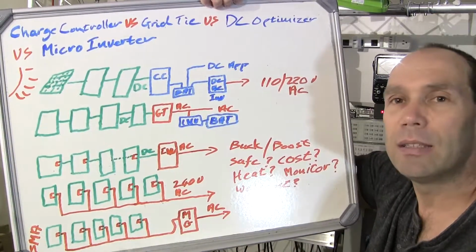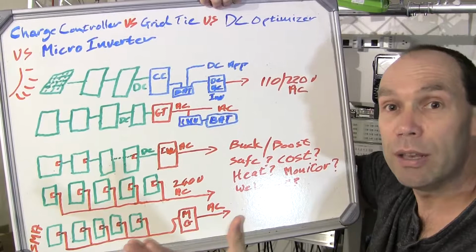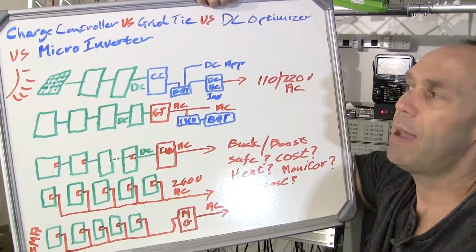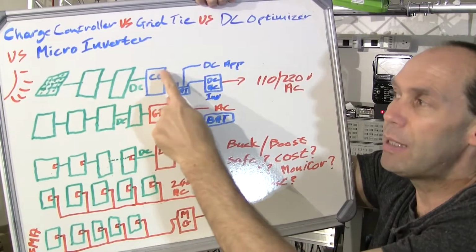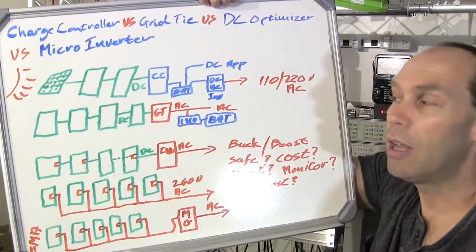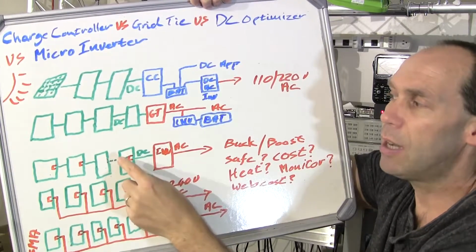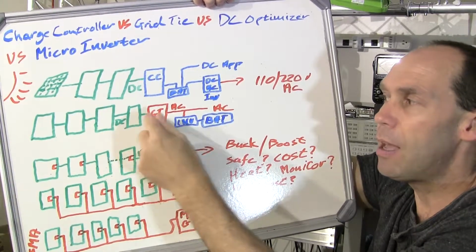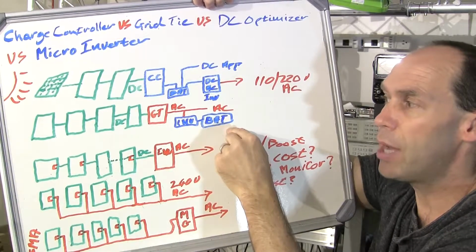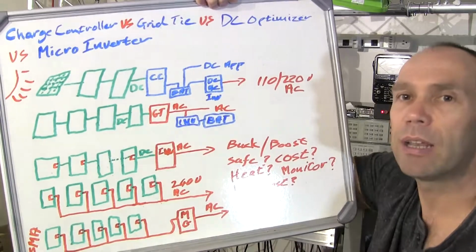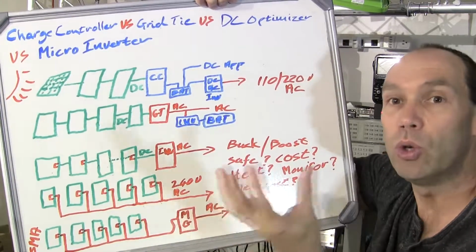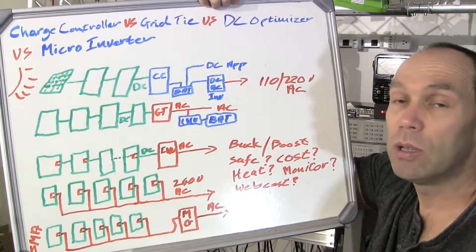So then in that case, let's say they want to use their energy at night time, they have to have a battery storage system. And then it makes sense to go straight from DC to charge your battery and then using that energy at night, rather than having a grid tie solution where you're going DC, AC, inverter, back to DC, charge battery, and then out of the inverter again at night. There are more losses involved. So you really do have to look at your usage and the potential losses involved.